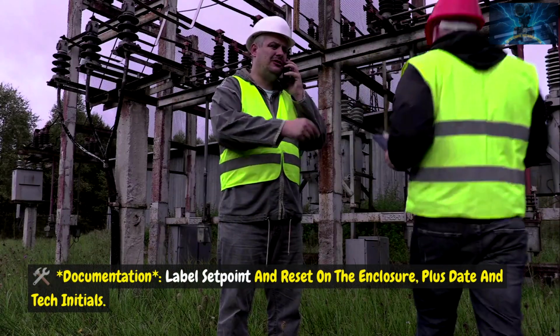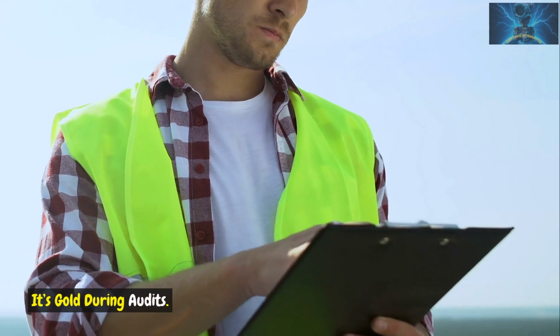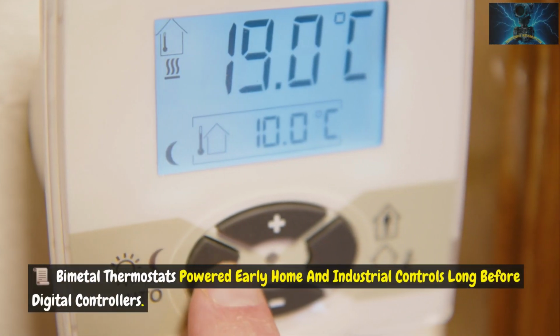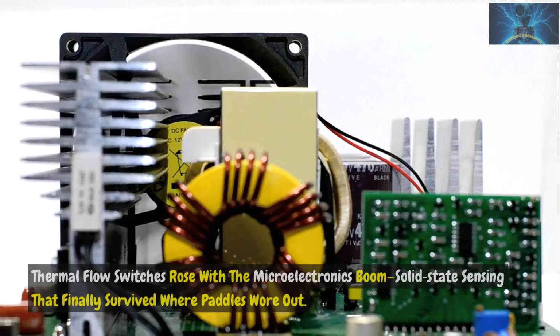Documentation: label set point and reset on the enclosure, plus date and tech initials. It's gold during audits. Tiny history moment. Bimetal thermostats powered early home and industrial controls long before digital controllers. Thermal flow switches rose with the microelectronics boom, solid-state sensing that finally survived where paddles wore out.